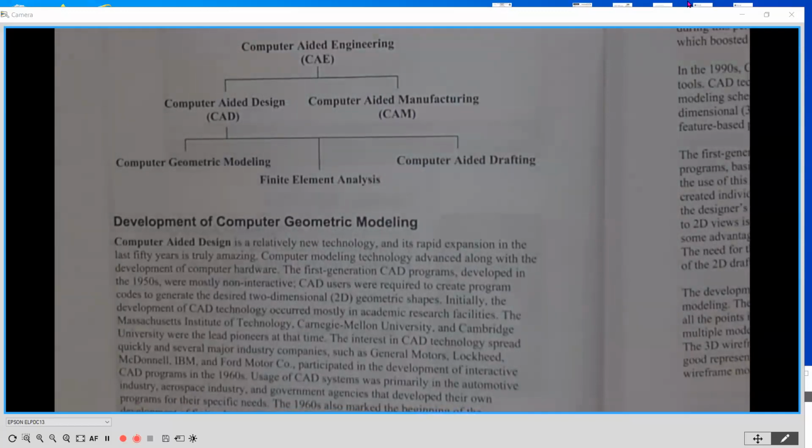There's also a lot of machine tools like laser cutters that need a path to follow. You can generate that in AutoCAD, send a DXF file, and a lot of machine tools will read that DXF path that's created in AutoCAD. So that's another application where it's still very viable. So AutoCAD hasn't gone by the wayside. It just isn't necessarily the answer to everything, and neither is parametric modeling, and that's why AutoCAD is still around. So we start you here with the 2D AutoCAD because it's the foundation. Okay. And you're also going to see it out in industry. It's not going away anytime soon.